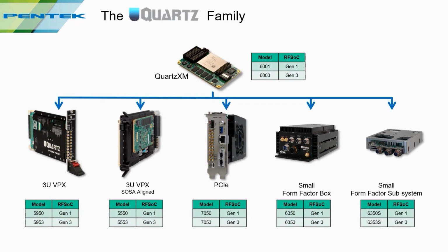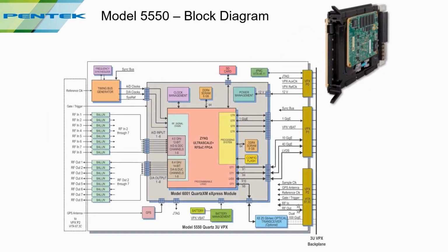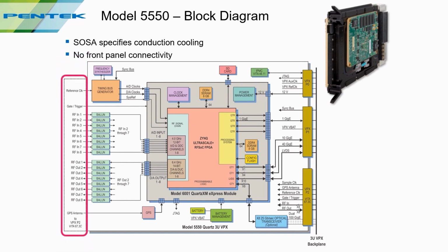So that's a quick look at the 3U VPX environment, but our Quartz family is available in a range of different solutions, from commercial to rugged and conduction cooled, like the SOSA aligned board. The block diagram looks a lot like the 3U VPX board I just showed, but SOSA is a specification being developed for rugged deployment in harsh environments, so the board is conduction cooled, and that requirement doesn't allow front panel RF connectors. So these need to move to the VPX backplane to this VITA 67.3C connector.